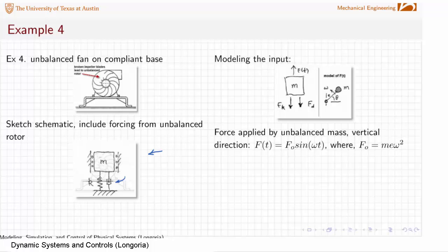At the end of the day, you could then proceed to do modeling as we've just done as a mass spring damper system. If we have a positive force, say, going up here with motion positive in the upward direction, the base stiffness and damping would be additional forces here. I'm not showing any gravitational force here. Sometimes in vibration problems, you may not put the mg force in there because you're just worried about motion about a certain point, and that equilibrium level could be found.